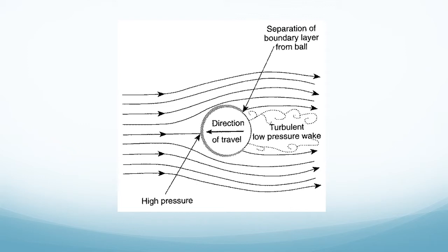Pressure drag is the front-to-back pressure differential. The side of the object with increased velocity will have decreased pressure, and the side of the object with decreased velocity will have increased pressure. Runners experience a drag coefficient of 0.9. A drag coefficient of 1 means that all of the fluid came to rest on the surface of the object, creating stagnation pressure or high pressure drag.